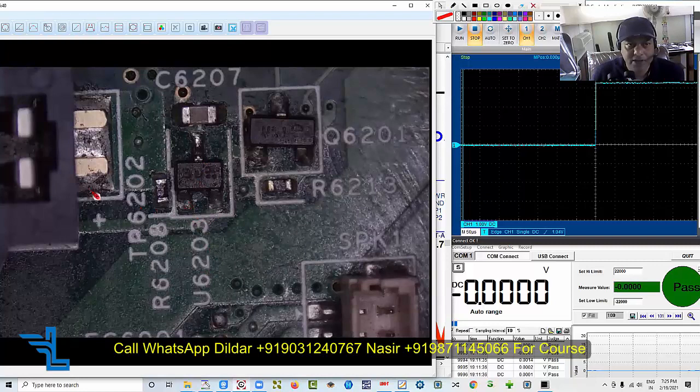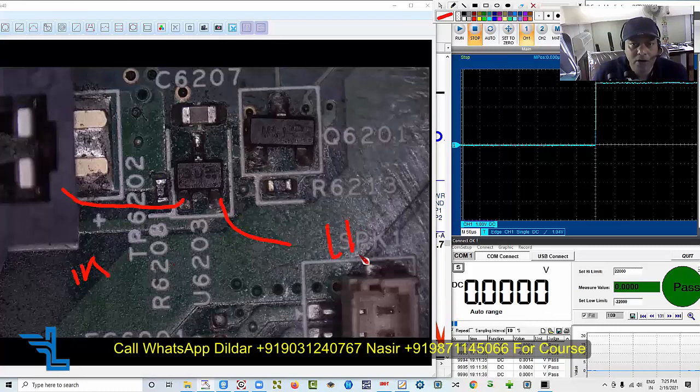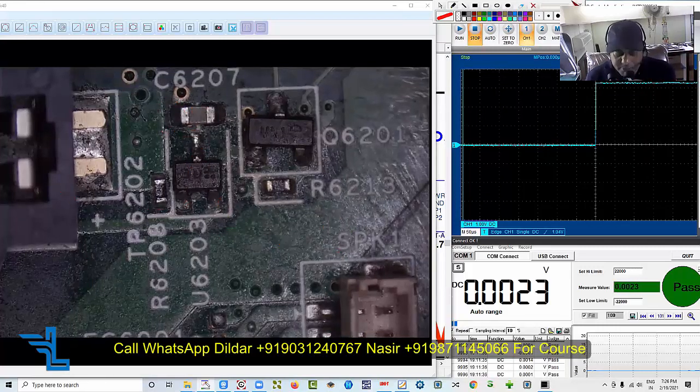One is connected with the RTC coin cell, and the other one is connected with the RTC cell with the help of a 1K resistor, and this is coming from the LDO, from the 3.3 and 5 volt, and both will help to switch this diode, and you will get 3.3 volt on this point, or 3 volt on this point. Now let's check this particular diode.